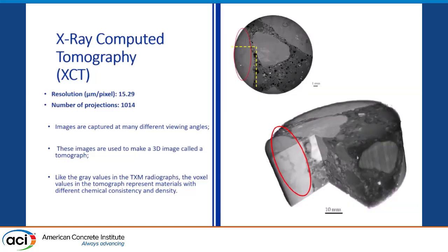In this case, after evaluating those samples that had higher iodine penetration after 2 millimeters, we could see there is a crack. You can see there is a crack on the aggregate, right? So it means that this crack provided a path for the iodine to penetrate into the sample. So we figured out that cracks can compromise the effectiveness of the silane and other sealer materials.